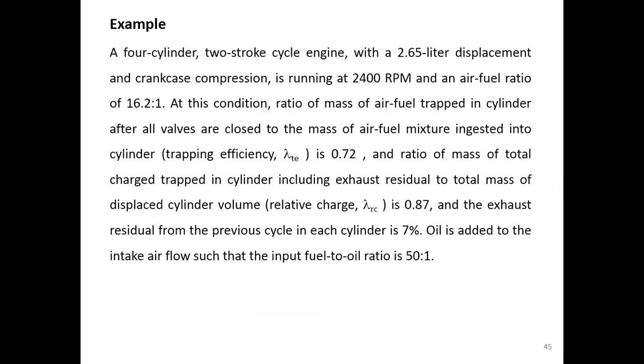So it's very simple: the actual amount of mass that flows into the cylinder does not equal the amount of mass that is trapped in the cylinder. That's why we have this ratio. And this ratio we call the trapping efficiency, which is equal to 0.72.